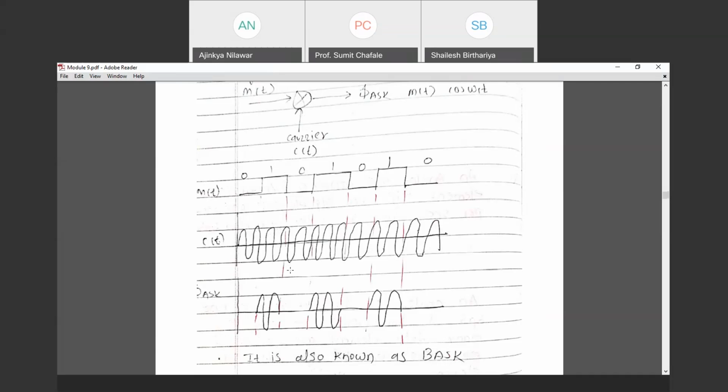Why? 1 bit, 2 raised to 1, 2 combinations, only 0 and 1, hence it is binary. If 2 bits are there per sample, 2 raised to 2, 4 symbols are there. 4 symbols means quadra. If 3 bits are there, we have octa. So depending on how many bits we are dealing with per sample, this nomenclature is given.